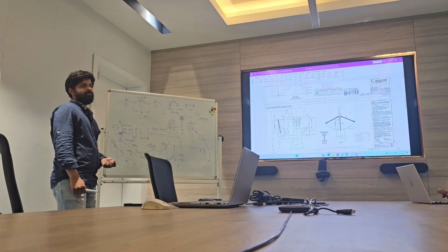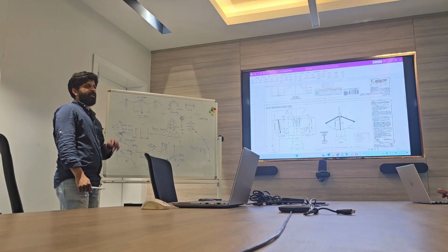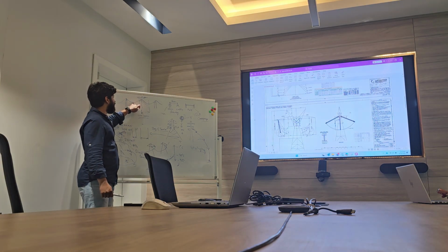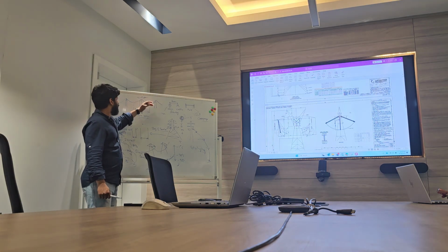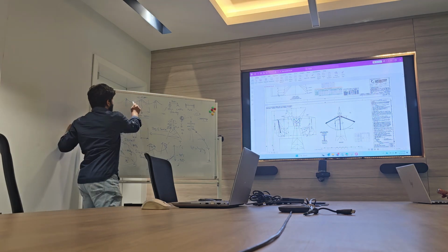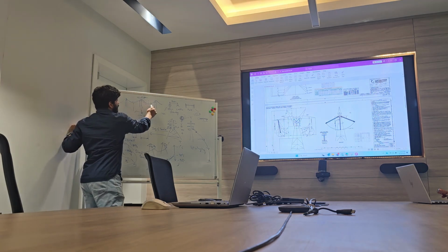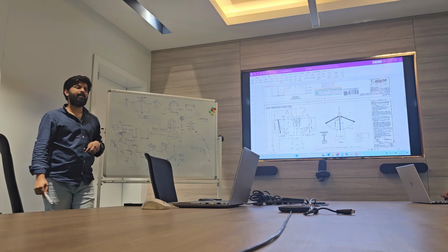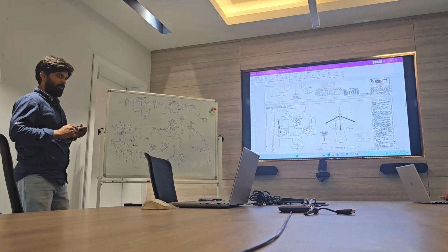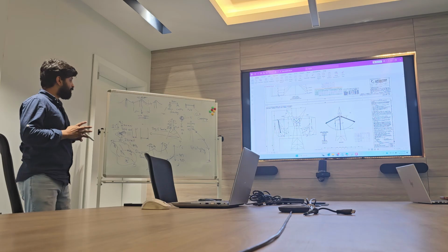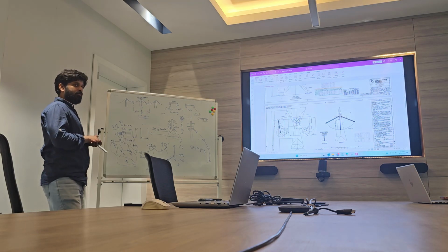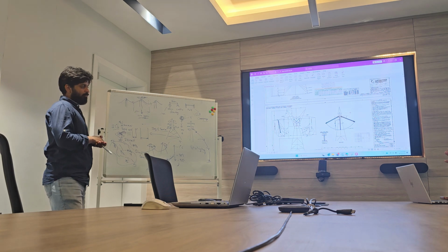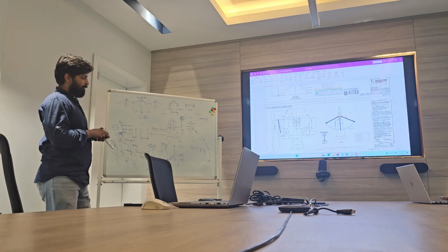So the lowest point. Let's say, if you have a slope area, here the center of gravity is here, there the center of gravity is here. Sometimes maybe a small difference, so a small difference between weight span and wind span will be there. Clear? There the tower has to be bigger because of more weight span. If the weight span is bigger, the tower has to be bigger. Let me know.